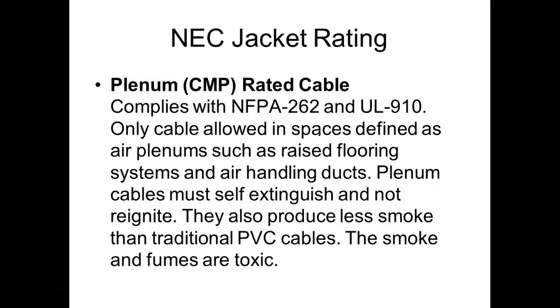Now, when we get into the jacket, we have different ratings on the outside jacket. Remember, the outside jacket is there to protect the cable from the environment. So we talked about what the plenum is. Anytime we have a suspended ceiling, the plenum is the space between the suspended ceiling and the actual ceiling. Originally, it was given the name plenum because it was used for the return for a lot of air conditioning systems. Even though our air conditioning system here at the college does not use the plenum as the return, as far as I know, it may.